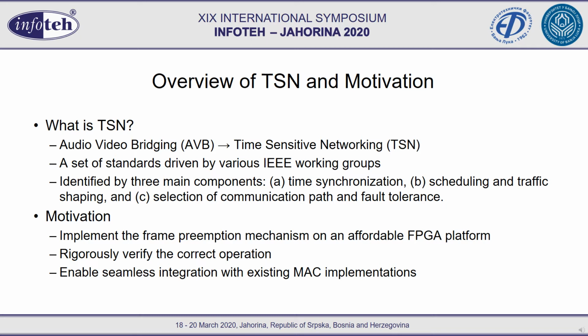Scheduling and traffic shaping is the second component, which is responsible for enabling determinism in the network. And finally, selection of communication paths and fault tolerance is the component that guarantees the reliability of the network. All in all, TSN is aimed at providing a deterministic and reliable behavior of Ethernet-based networks.